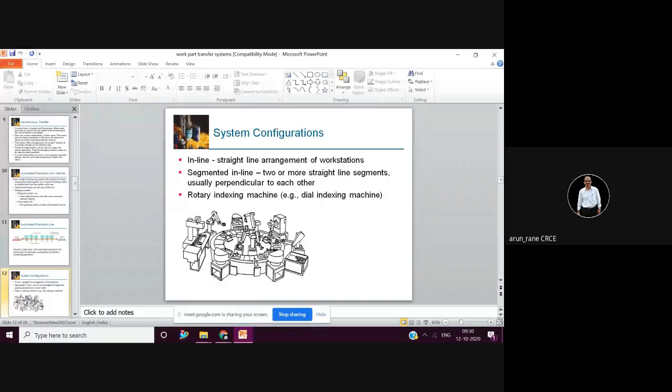If this fellow takes 30 seconds, and this fellow is taking say 1.5 minutes, the manager can ask that once you complete your work, you go and help him. So that 1.5 minutes can be brought down to 1 minute. And then again go back to your workstation because the components are coming. This is possible in rotary only because the movements are less.